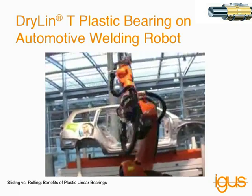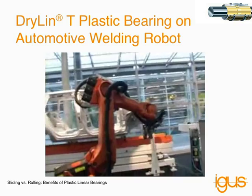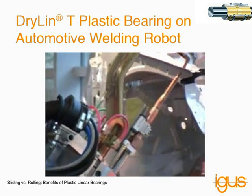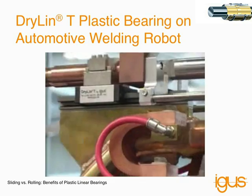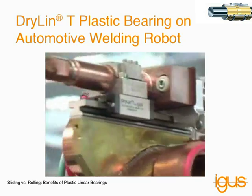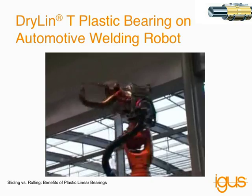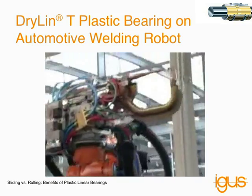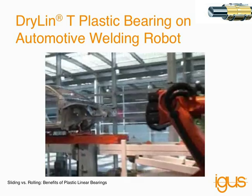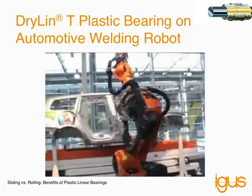Ball bearings used in this application, right when the weld splatter would hit the rail, could embed themselves into the ball bearings, causing damage to both the ball bearings and the rail itself. So this is another application where DryLin was successfully able to replace ball bearings in harsh environmental conditions. Probably not so much for this type of robot, but for a lot of robotics where the robot's not quite so large, another ideal benefit of a plastic part with an aluminum rail would be the weight reduction as well.